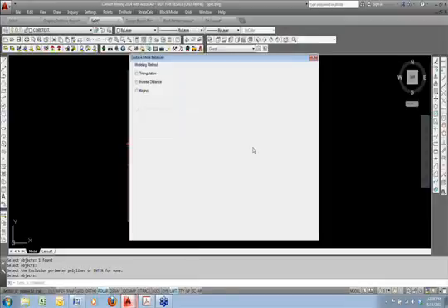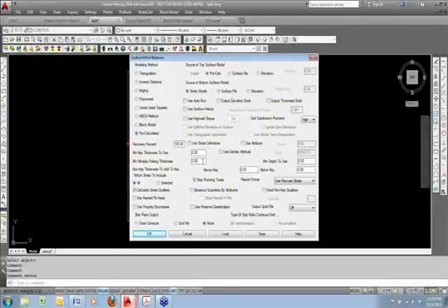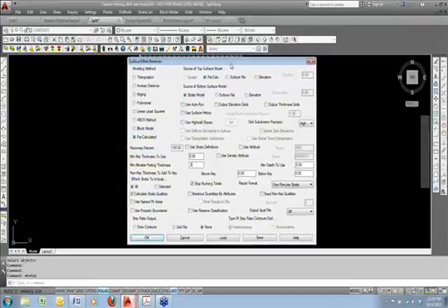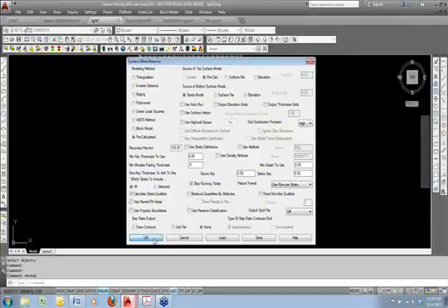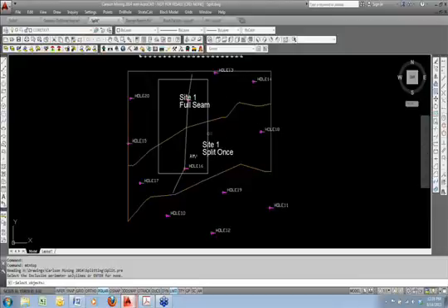So let's go back to surface mine reserves. We have this minimum mineable parting thickness. So the answer to the question is yes, it is in the tonnage calculation. I'll put in 0.5. I will allow up to half a foot of parting to be mined with the key tons. So I'll hit OK. Choose that. Select the inclusion.